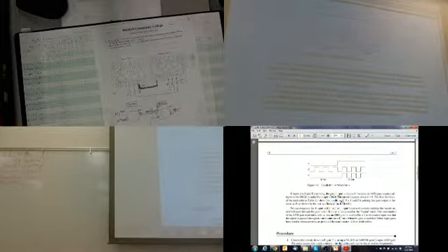So what you do is you set that up. You ground the black end to your ground plane. Now I use the blue bus as the ground plane. I use the red bus that goes all the way across as the VCC, plus 5 volts. Okay, now before you do that, you're going to turn on this instrument. This is the oscilloscope, and I know you guys have used this before, but it's just a quick tutorial on the way you work this thing.